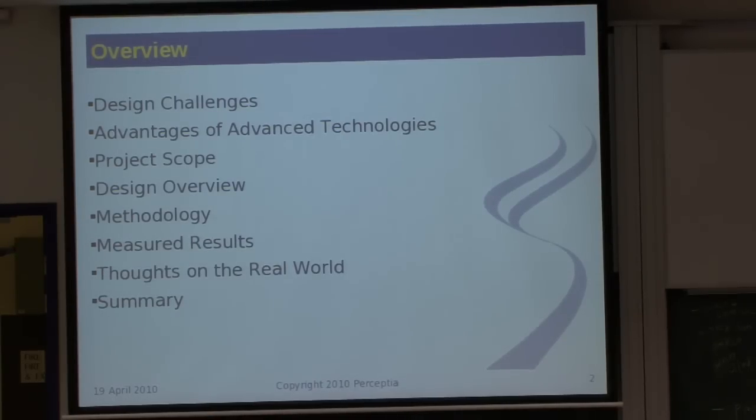My main role is actually in analog design. Perceptu's main focus is on SerDes, serializer-deserializer, talking maybe 10 gigabits per second across 1 meter of PCB trace. Next year we start thinking about 28 gigabits per second, but not until they give us 28 nanometer processes to work with.